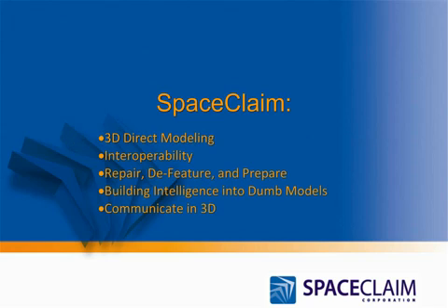SpaceClaim is a new solid modeling tool that uses direct modeling technology to let you work with 3D models in ways you've never thought were possible. It works using interactive tools that directly create, edit, and parameterize designs regardless of origin. SpaceClaim is complementary to feature-based modelers, with robust translators to read and write a broad variety of CAD formats. It provides streamlined tools to quickly remove small faces, create mid-surfaces, and extract volumes for CFD.